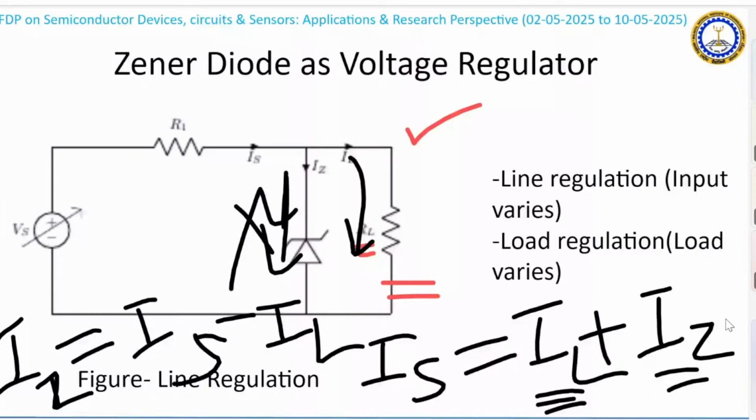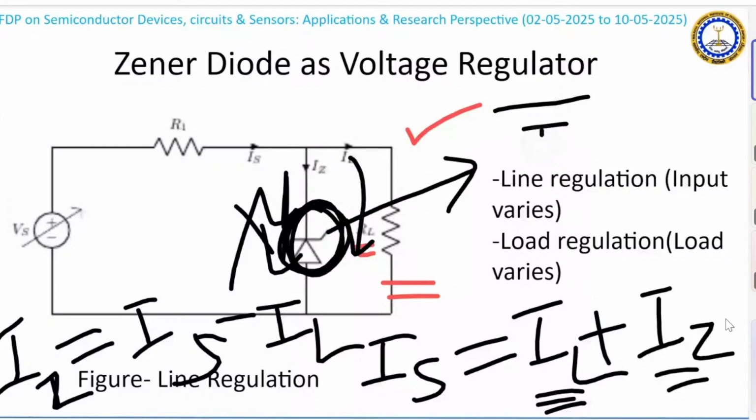So basically, see, whenever this is in the Zener domain, the resistance offered by this is approximately 0 because it is working like a constant voltage device. So you can replace it by a constant voltage, that is nothing but Vz, and a series connected resistance, but the resistance offered by the Zener diode, Rz, is equal to 0 in the Zener mode.